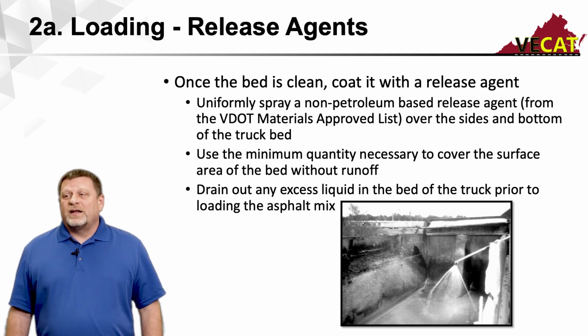If you do have that, you should raise the truck at a designated site just enough so that the excess material runs out, because the goal here is not to have a lot of ponding, just a thin layer of lubrication to allow the mix to come out of the truck smoothly.